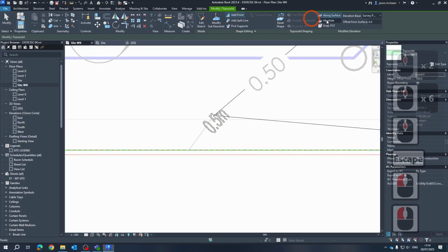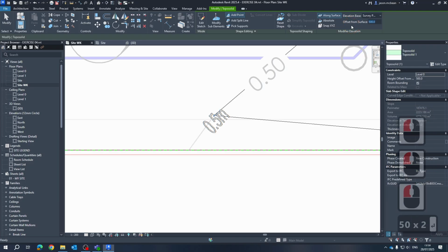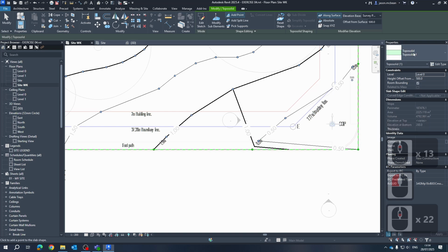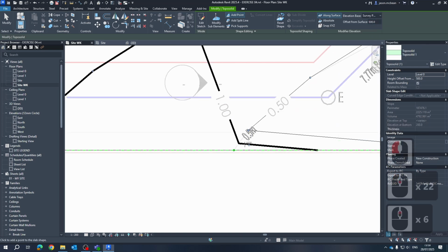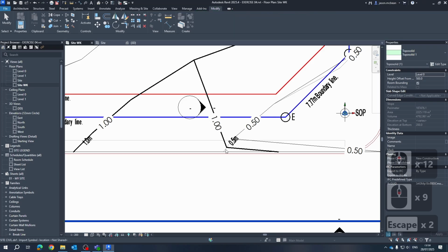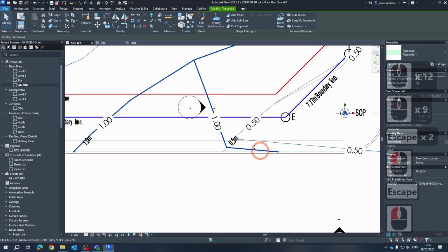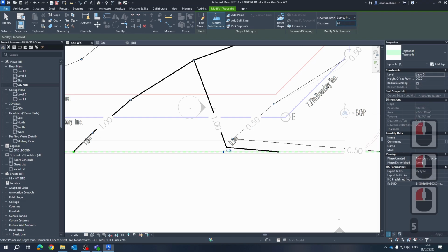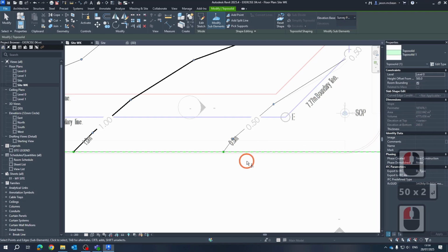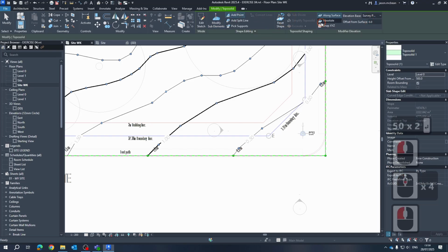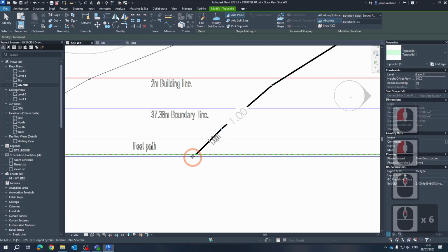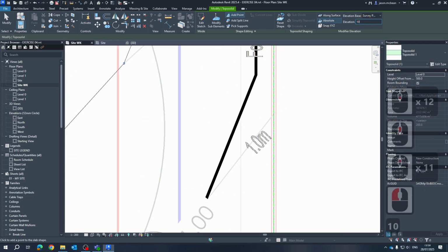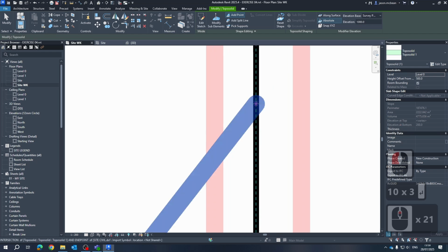So select the topography, add point, 500. So I'm going to add that along this line as accurately as I can. Okay, make sure 500. You can see sometimes if there's an error, edit, so let's just make sure, 500. Okay, it must be 500, very important. So I'm going to go and say add point, remember, absolute. So I see that my meter one's not correct there, so I need to add a meter one over here, 1000. And try and snap this point as close as possible.